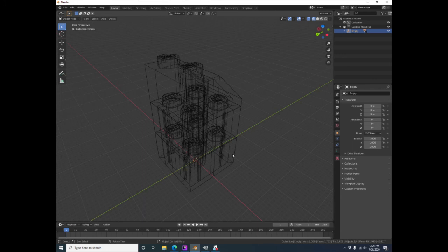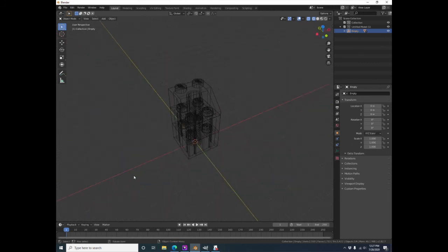Tabletop Simulator has a hard limit in its programming for each model of 20,000 vertices. For this model, we're well underneath that limit. But in general, it's good to retopologize these models, try and reduce the number of vertices that's in the mesh, so that each model is not taking up too many resources in your system, especially if we want to have 100 of these.